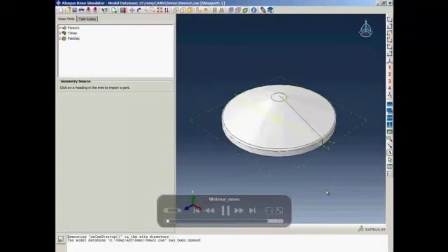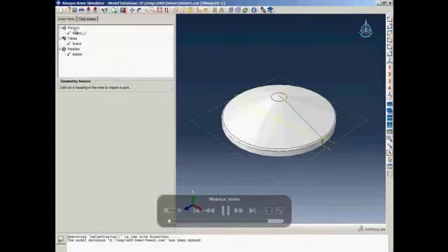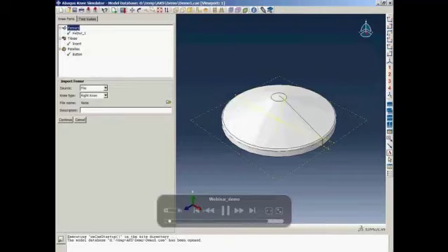So once the database is opened, the user can look at the interface of the Abaqus Knee Simulator. So go through the Knee Parts tab and the Test Suite tab, which is a repository of either implant components or Test Suites. To import a femur component, I just click on the femurs. There are different sources supported by Abaqus Knee Simulator that include the neutral file, CAE model, or CAD interfaces.